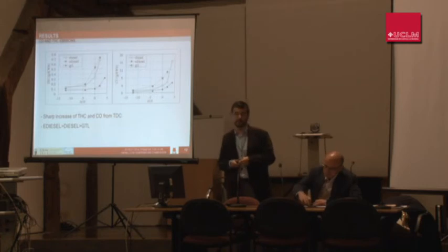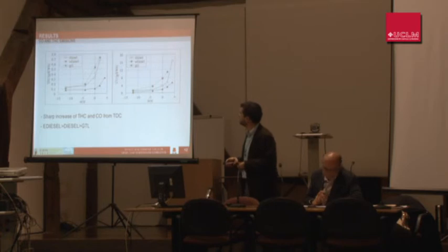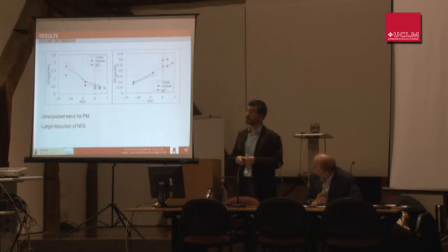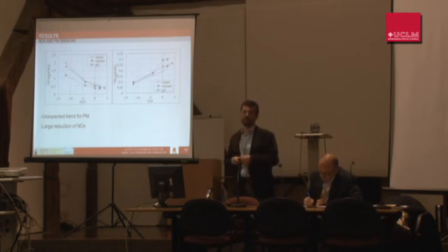When taking a look at carbon monoxide and total hydrocarbons, we see a really, really sharp increase after top dead center. That was expectable and is really common with LTC processes. And what we did not expect were these results. We expected these ones, which are good. We are decreasing NOx at a really large rate. We are using both high EGR and really delayed start of ignition, so we were expecting really low levels of NOx. But we were expecting a change in these values. We were expecting that particulate matter would decrease after top dead center, and we have not obtained that.